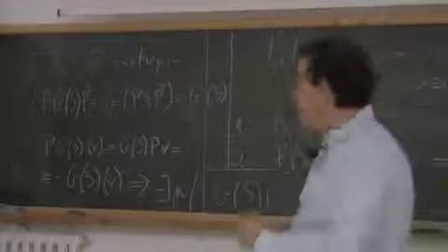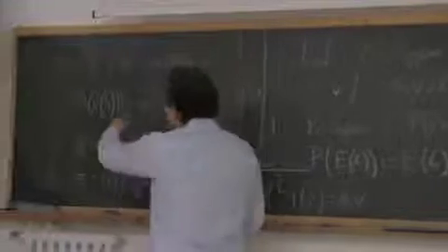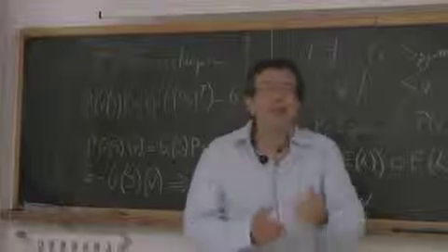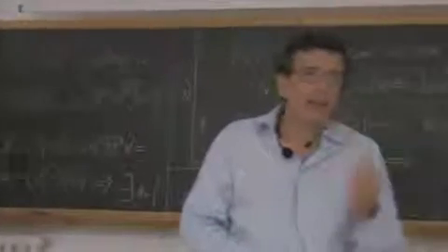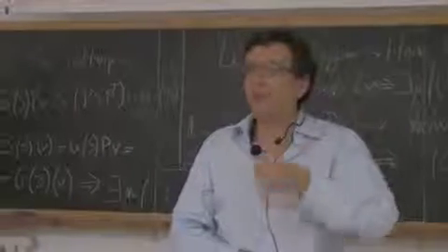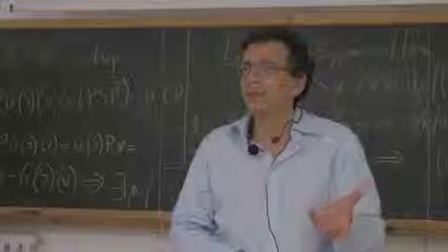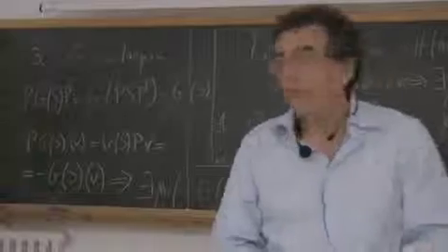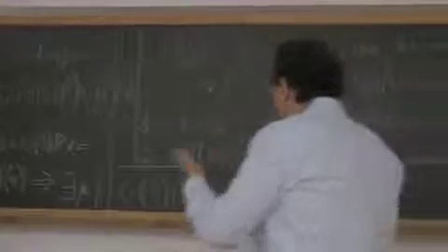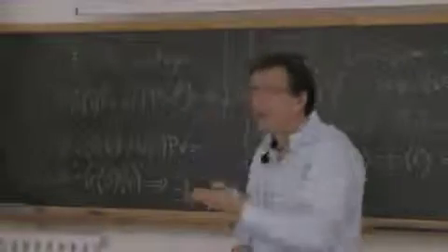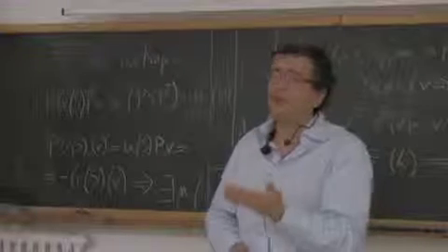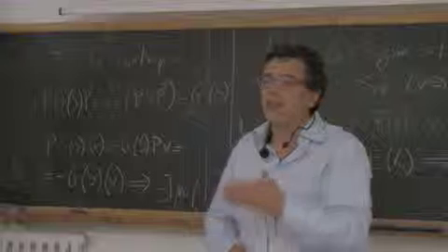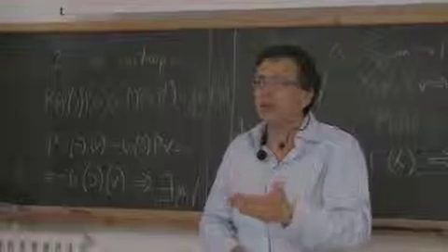Even if the map G is different in the sense that its physical meaning is different. Okay? In the case of solids, the constitutive equation is giving you Piola stress in terms of deformation.